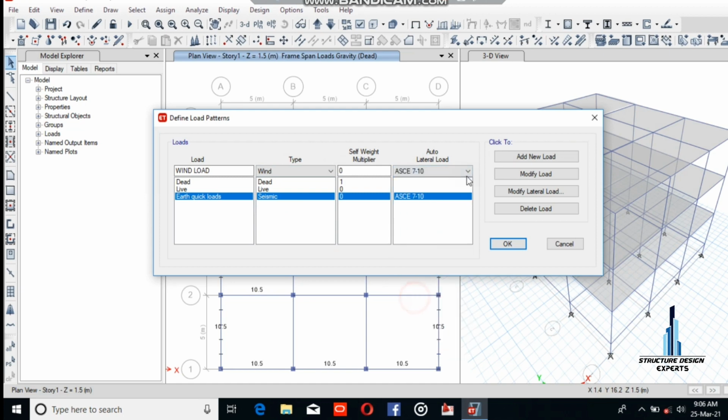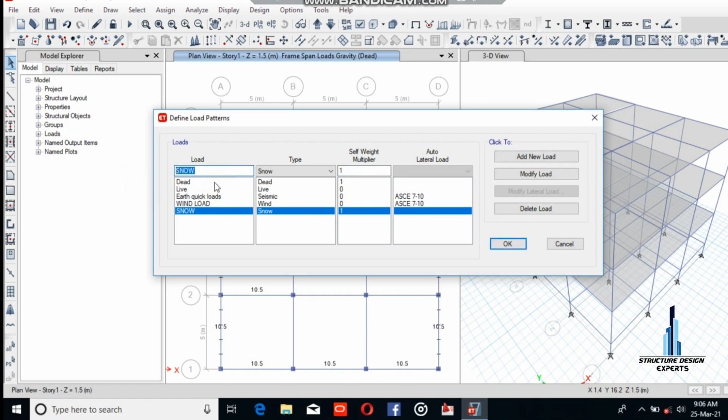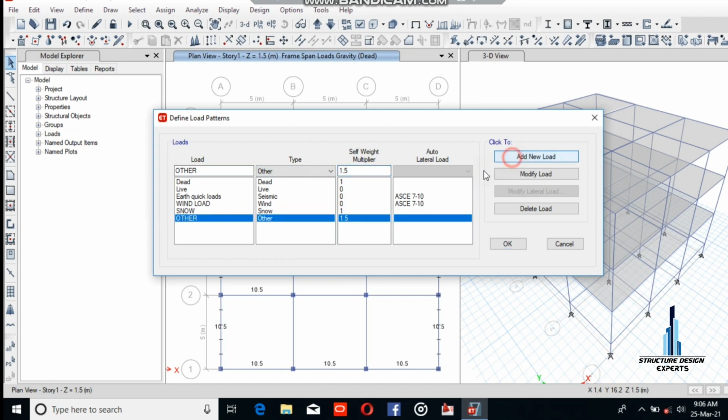And as per ASCE 7, for example, now we use the snow load. If you are in a snow area, you should select snow. If you don't have snow, you leave this. And the rain and other loads, you should include in the live load, because in some areas local authorities and societies of engineers direct that the rainwater load is included in the live load, as a specific amount of load.